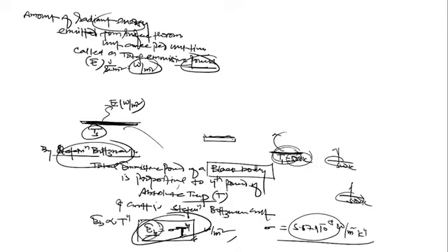If 5 bodies are there, and 4 are real bodies and only one is a black body, all at the same temperature, which body will emit the maximum emissive power? The black body. And can you calculate the amount of maximum emissive power if the temperature is known? How? By the Stefan-Boltzmann law, because the Stefan-Boltzmann law is only for a black body, and this will provide the maximum or upper limit of emissive power.